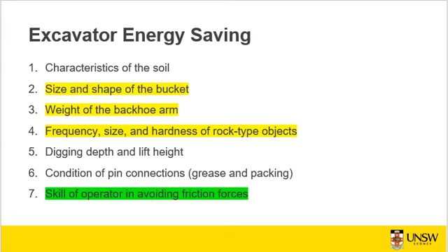So some factors to consider would be the size of the excavator, the working environment, and related conditions such as soil type and accessibility. So how much room is available for the excavator to perform optimally? Another factor is the operator, right? They must be licensed, competent, skillful, experienced with operating the specific excavator, because not all excavators are the same.